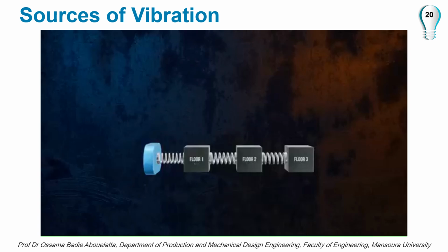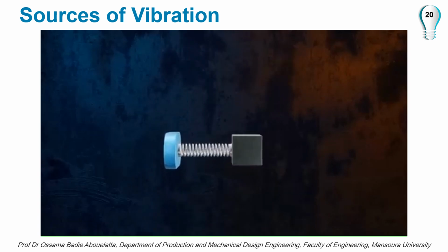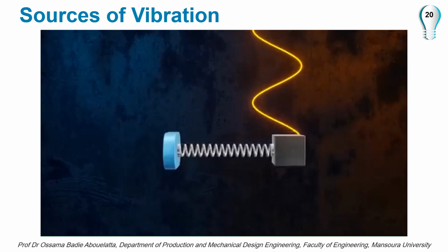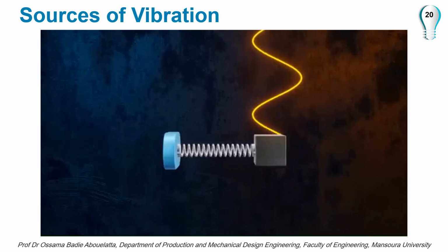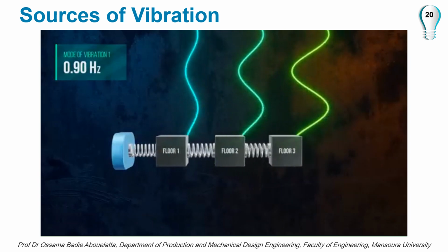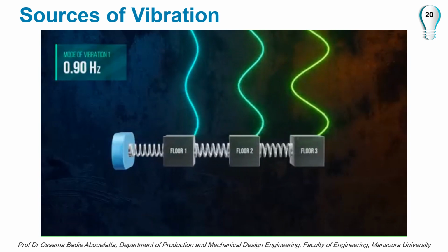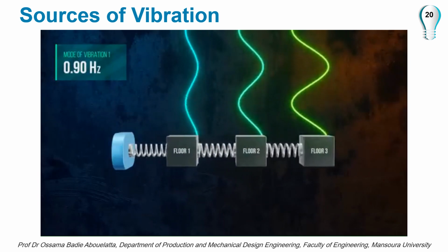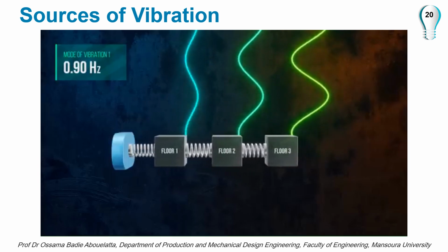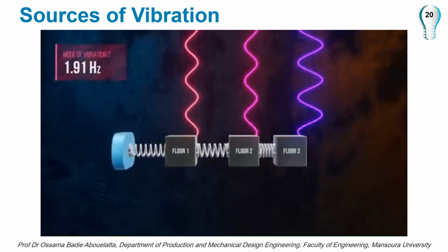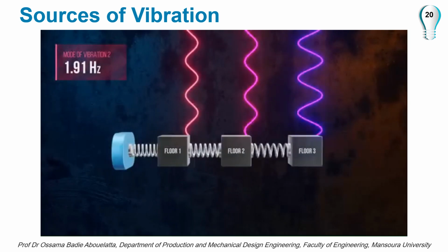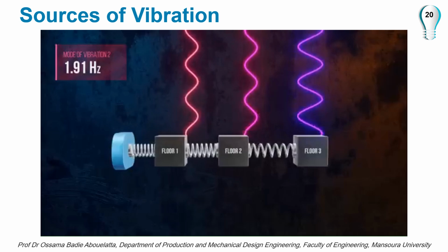A single degree of freedom system has one natural frequency and can only vibrate in one way. But since our model has 3 degrees of freedom, it will also have 3 natural frequencies, and at each natural frequency, the system will vibrate in a specific way, which is called a mode shape. Exactly how the system vibrates in practice will depend on the initial conditions that are applied.